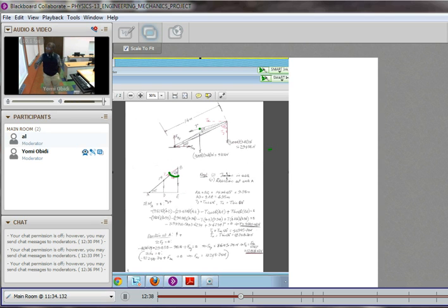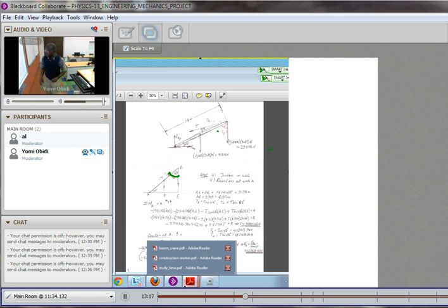There are different ways you can go about it, but probably a simple way is to look at this scenario that we have, this T, and use the information that we know the orientation to the x-axis, and we know the orientation to the y-axis. We already found out that this is 60 degrees. So if it's 60 degrees to the y-axis, then the y component, T sub y, is just going to be T cosine 60 degrees, and T sub x is going to be T sine 60 degrees.